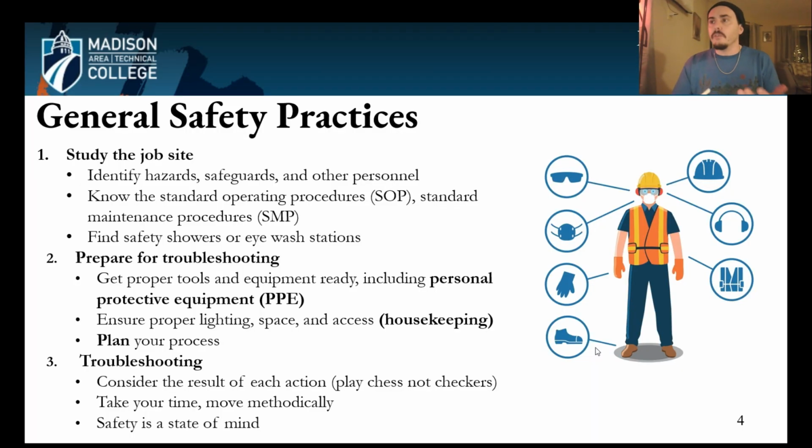All right, so some general safety practices. I broke this down into 3 steps. Study the job site prior to troubleshooting. Prepare for your troubleshooting using the information you got from studying it, and then the actual troubleshooting itself. So when you study the job site, you want to identify possible hazards and also safeguards and basically understand where everything is relative to your workspace.